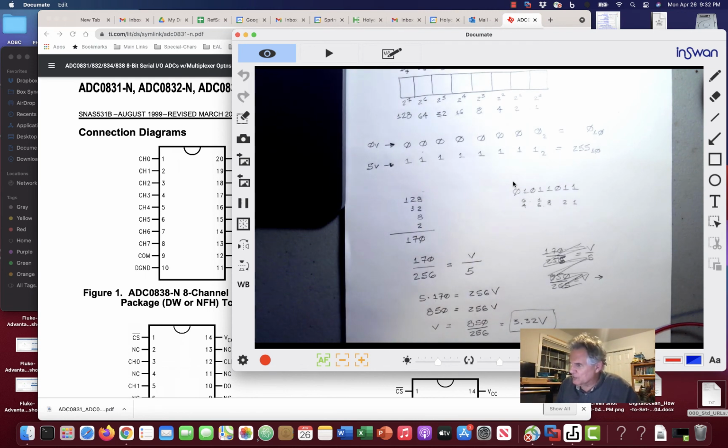And we converted some continuous time signal coming off a potentiometer, which could have been a thermistor, could have been a pressure sensor of some kind, could have been any kind of sensor. It could have been a 4 to 20 milliamp current loop where when you convert it to a voltage, you bring it to the analog to digital converter. You do the magic interfacing by reading the data sheet and all that kind of stuff.